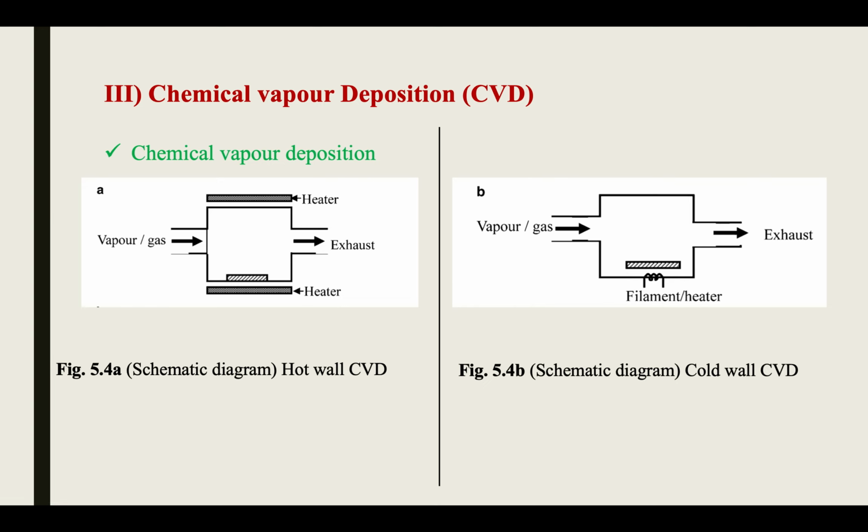Usually a particular gas pressure is used inside, ranging from 100 to 10^5 pascal. Growth rate and film quality depend upon the gas pressure and the substrate temperature. At intermediate temperature, growth is limited by mass transport, that is, the supply of reacting gases to the substrate. Here the reaction is faster and the supply of reactant is slower. At high temperature, the growth rate reduces due to desorption of precursor from the substrate.